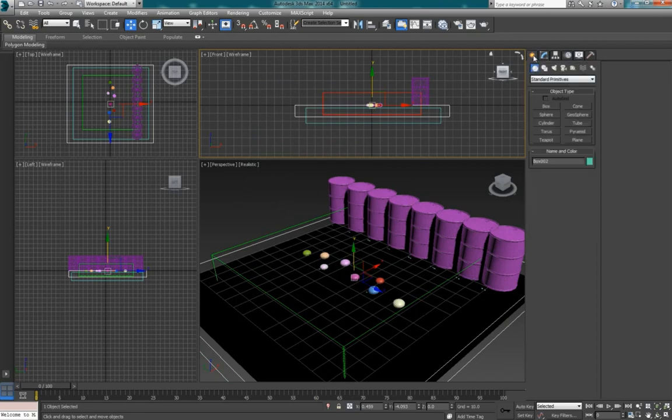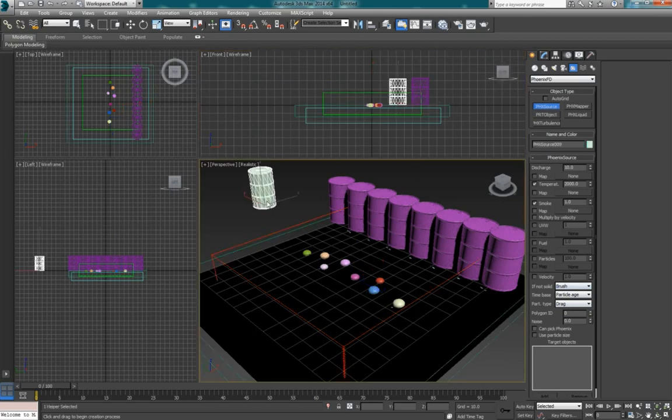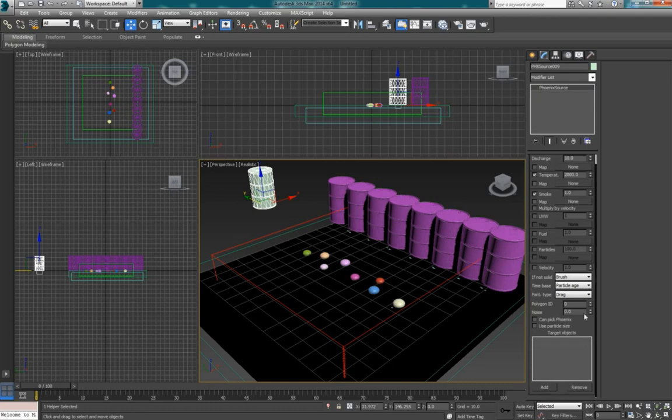I'm going to use a brush source in order to create a thin layer of smoke on top of the solid ground, and this will help us get a more realistic effect on the simulation, and this way the explosions will interact with this smoke and they will draw it in as they rise up, and they will also create shock waves on it at the moment of their explosion. So you will see the effect finally, and I think you will like it.